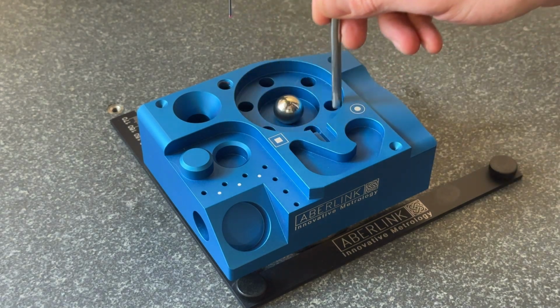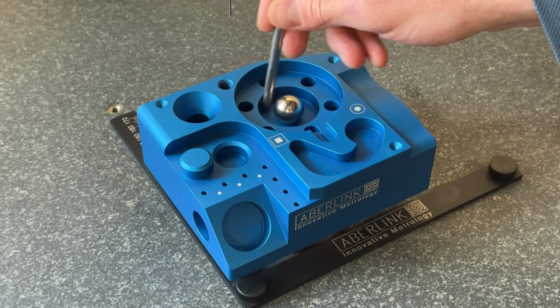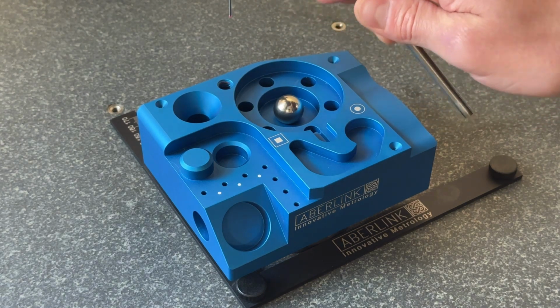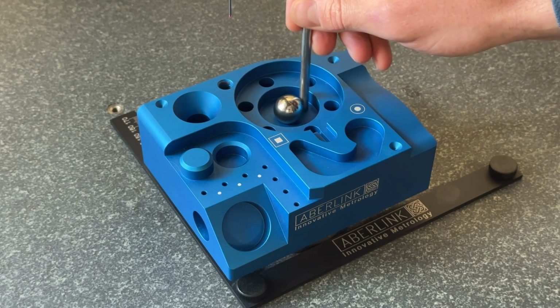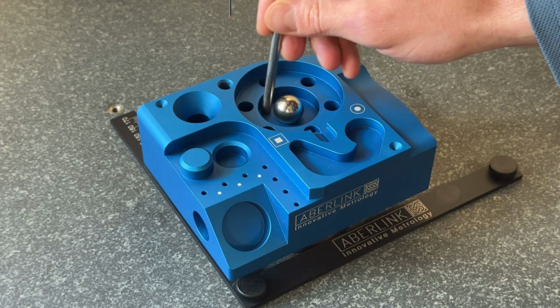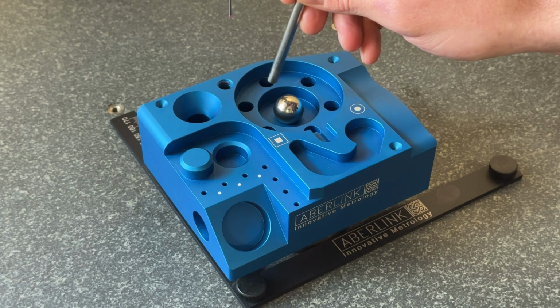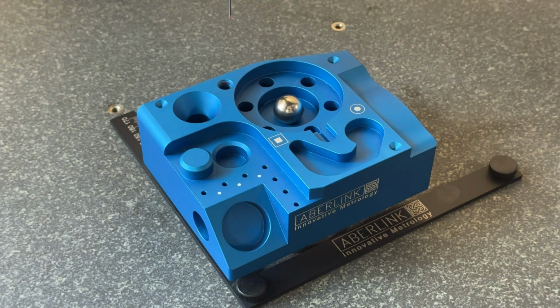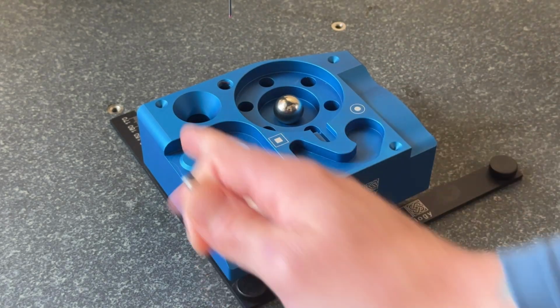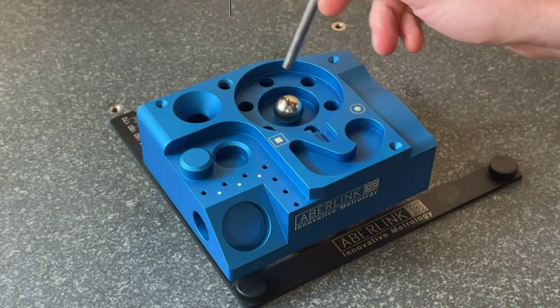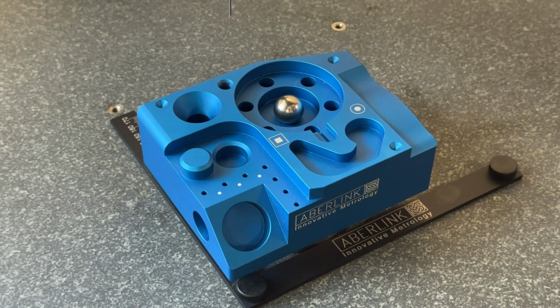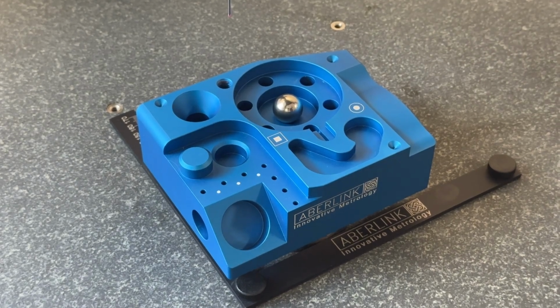So say this pocket with all the PCD holes and this groove are all done in the same operation. I want to link the measurement path and the template of these circular planes, so an inner and outer, to be linked to this bore. So the position is no longer linked to the datum or the reference in the corner. It's going to be linked to this larger circle. So let's dive in and have a look at that.